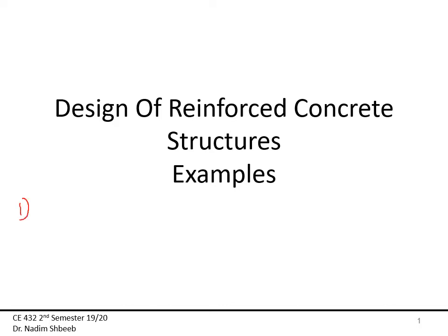The first one is usually what I call a fresh design. You have no clue. Then by that you will have B, H, and the area of steel, all unknowns. Okay, all three of them. The way to approach that is you probably will have some ratio between B and H, like we showed you. Let's say D is equal to 2.5 B. So there's a relation between B and D, obviously, from which you can get H.